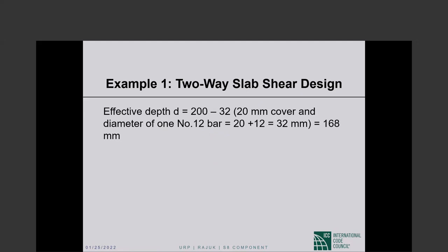If you are finicky, you could design the slab in one direction, so one layer will be below the other layer. So in one direction of the slab, you could take d to the centroid of the lower layer, and in the orthogonal direction, you could take d to the centroid of the upper layer. I do not know anybody who does that.